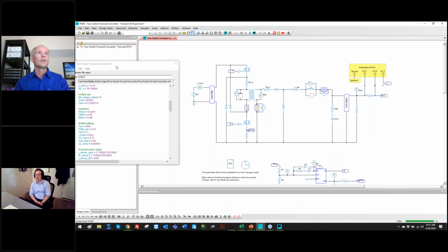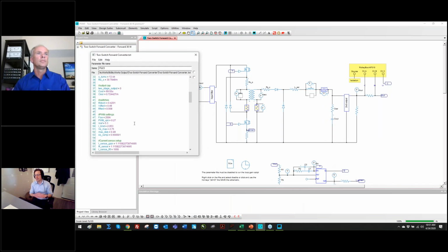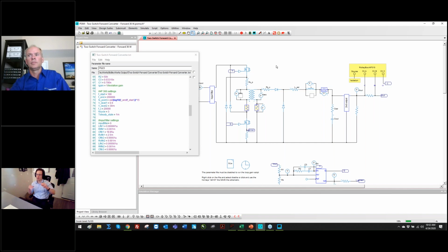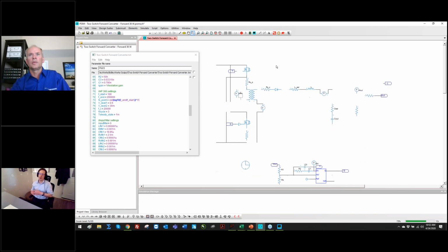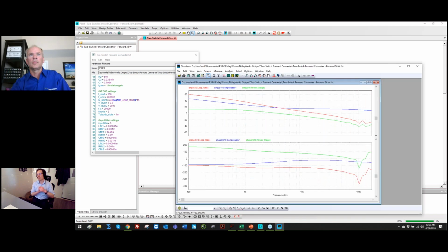was in speeding it up was to ensure that we're running the system to steady state, and then we're injecting the perturbations. And one of the things that we can do with PSIM is multi-core the simulation. PSIM doesn't break the matrix apart to run on individual cores. So one simulation doesn't get broken apart, but what is happening is that we're running the individual simulations on the extra cores. So the more cores you have, the more simulations you can run simultaneously, and then potentially the faster this can go.